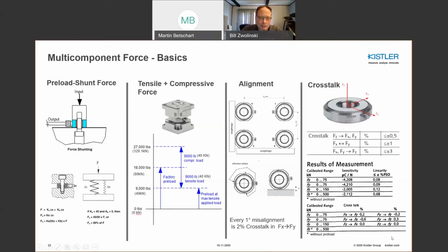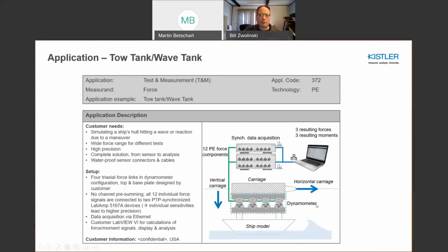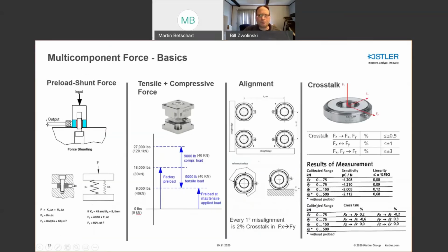In many cases, there's no need to do any compensation matrix for crosstalk for piezoelectrics because they're so inherently low in crosstalk. Unlike, say, strain gauge technology, where there might be compensation matrices for high crosstalk. So a little less bookkeeping, a little less work involved when you get to the solution of crosstalk.